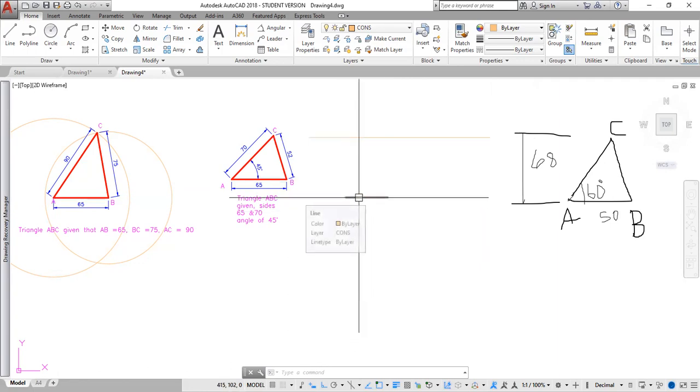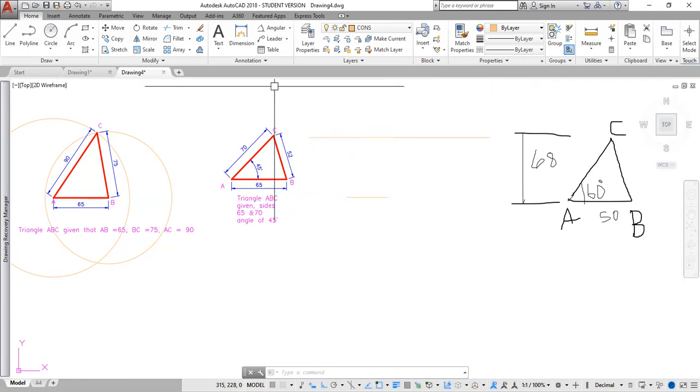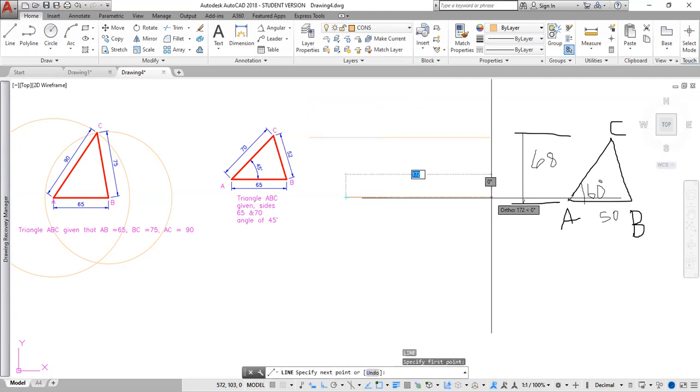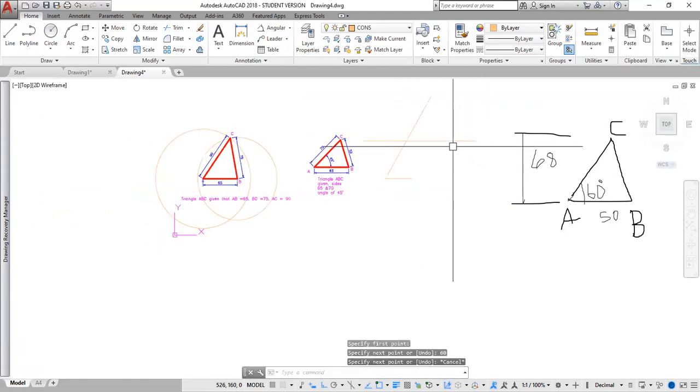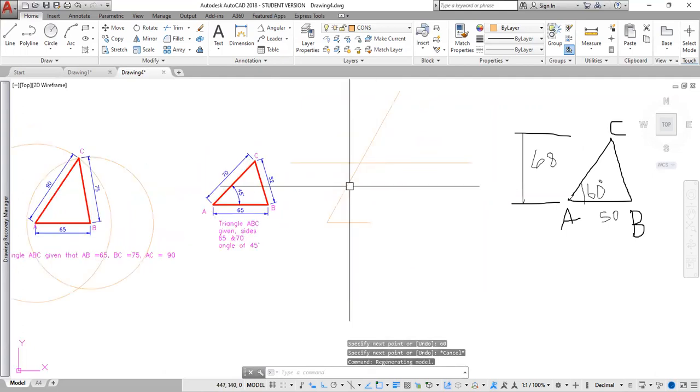For this, I'm going to type L for line, enter, specify here as my first point, left click here, drag this to a suitable distance, then press which key do I press to change from the length to degree? Sure, tab. The tab key, lovely. Then I enter 60, then enter, then escape. So that now draws my line at 60 degrees.